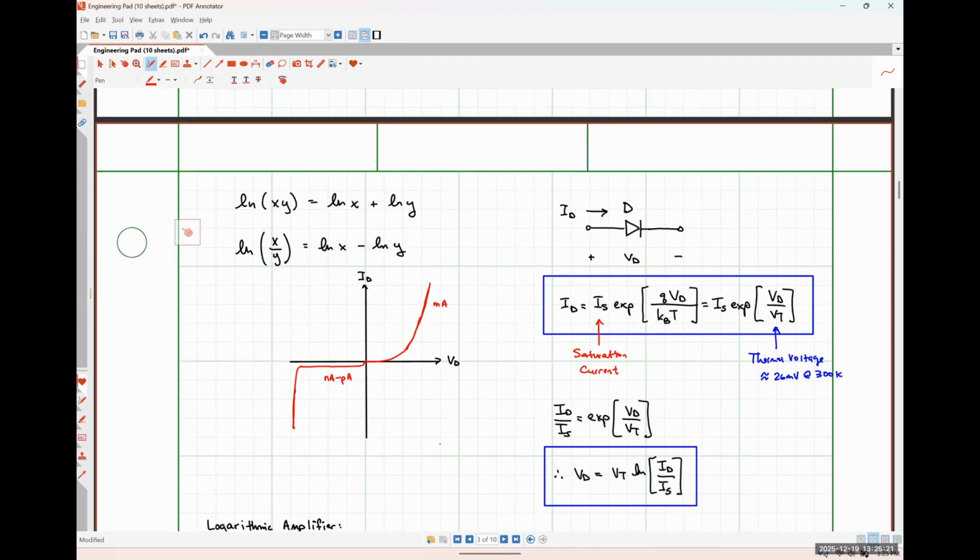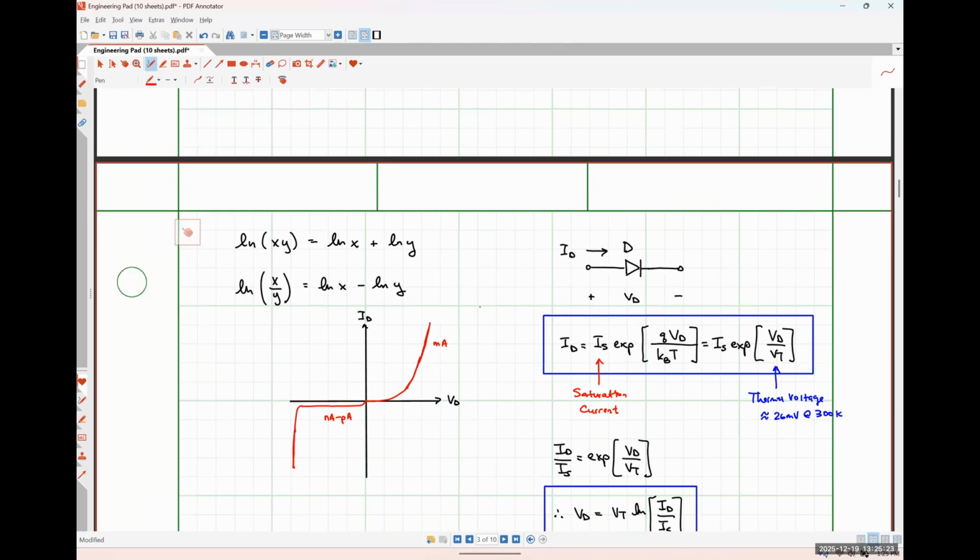So coming back up here, I need to take the natural log of one input signal and the natural log of another input signal, and then add those guys together. So how might we do that? Cascaded amplifier. So I'm going to have to do a cascaded amplifier, but how am I going to do the addition specifically? So some sort of summing amplifier. Absolutely right.